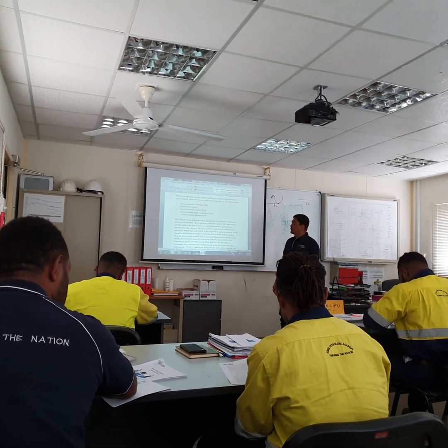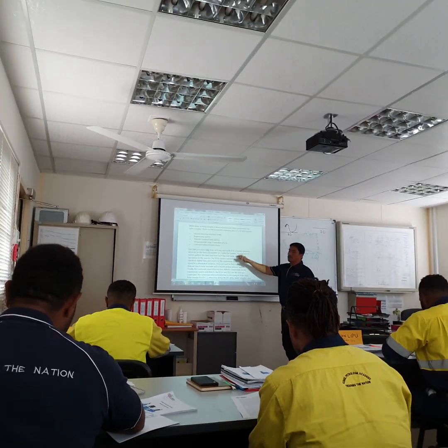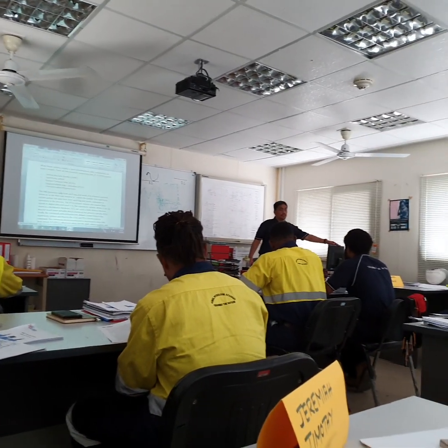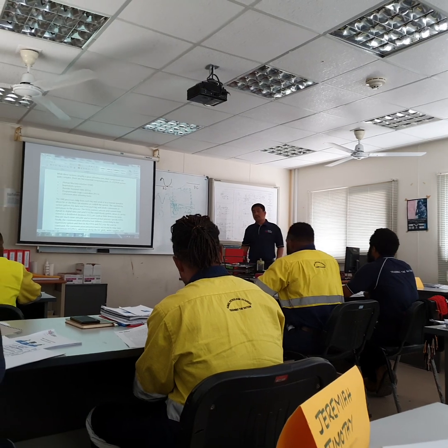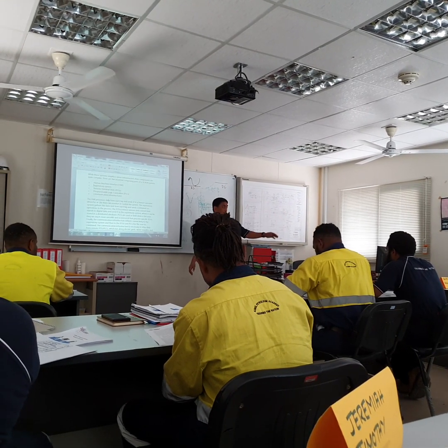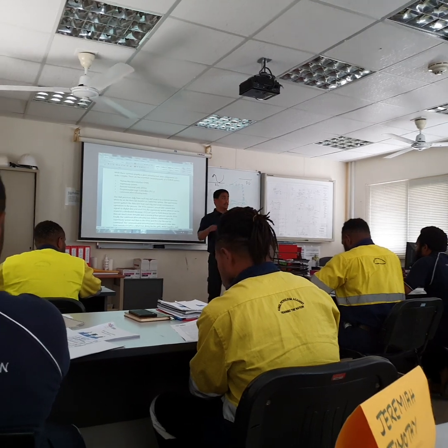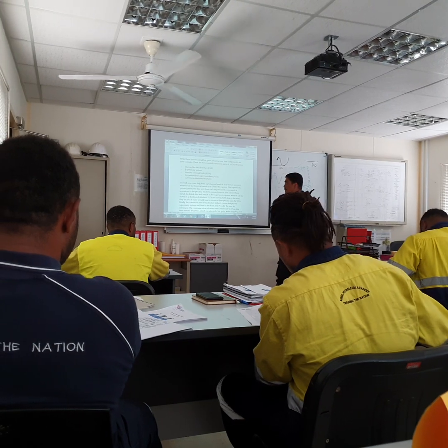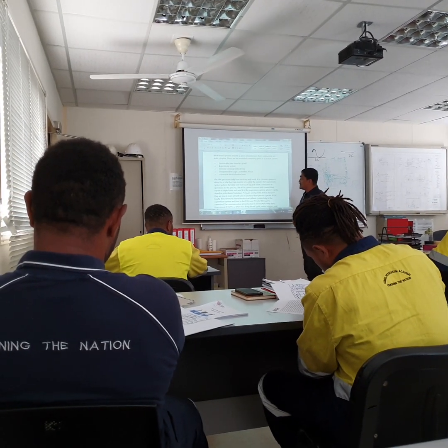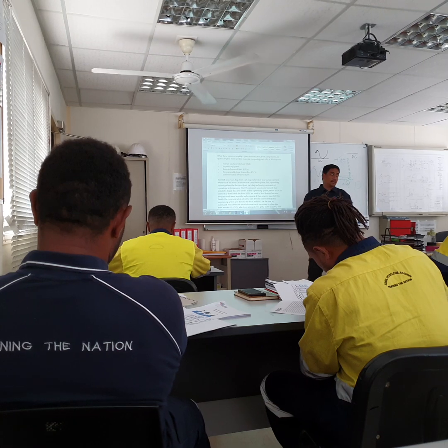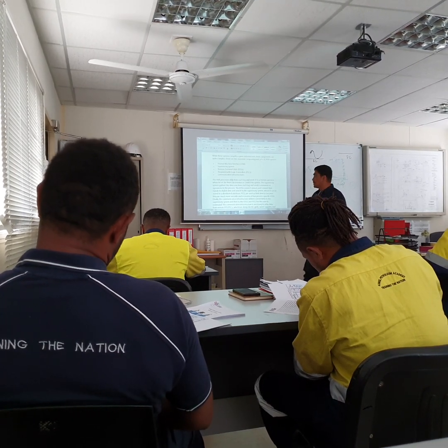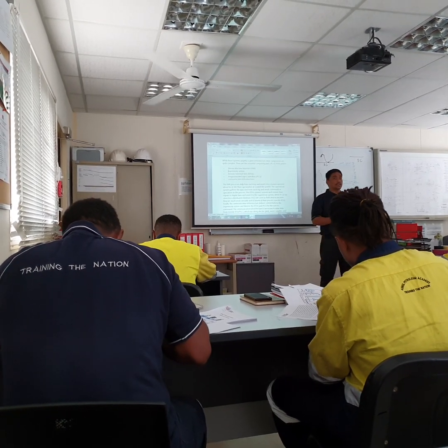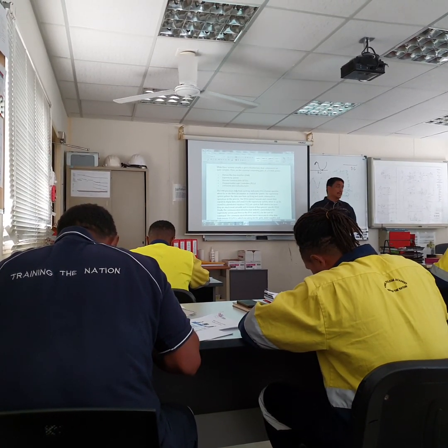Communication infrastructure. Okay. Just to explain, a human-machine interface, you'll find it like this. This is a sample of a human interface. The computer LCD. So you communicate with that, you control it, you will see all the process and what is happening on the plant using the human interface. Now next is supervisory system. So there's a SCADA system that supervises it. There's a program. Remote terminal units, those are units located at the marshalling cabinet, at the control cabinets.